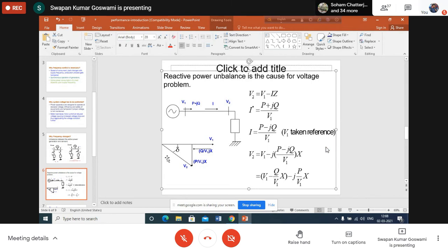Here, during the consideration of impedance, why are we not considering the capacitive reactance? Capacitive reactance. Where the voltage drop occurs, is there any voltage drop occurring at the capacitive reactance? That is from conductor to conductor. And if we show the equivalent capacitance, we show it from conductor to neutral, phase to neutral. So current is basically flowing through the conductor, not through the capacitance. Whenever the load current is flowing, it is flowing through the conductor itself, from the generator, through the conductor to the load, not through the capacitance. So there is no question of voltage drop in the capacitance.